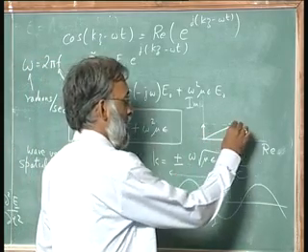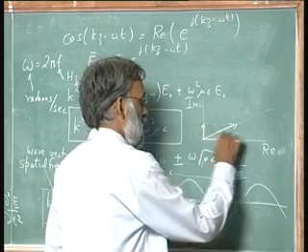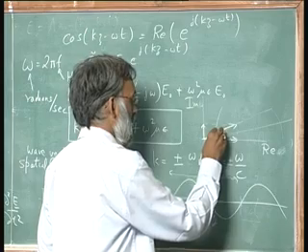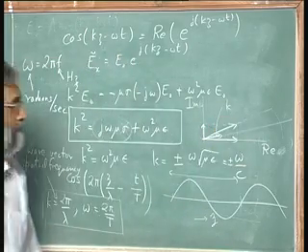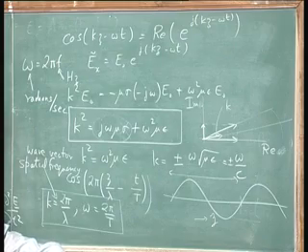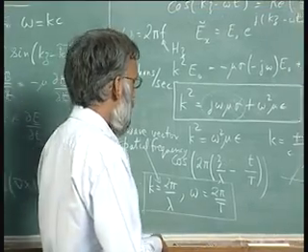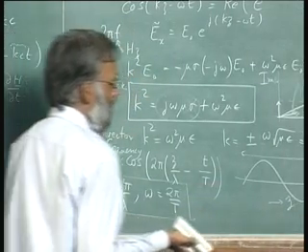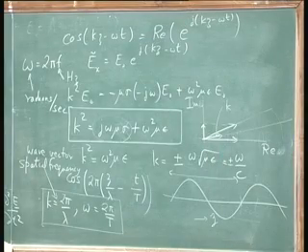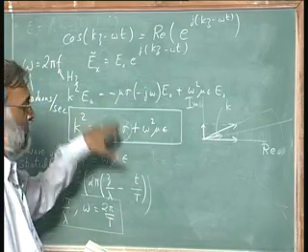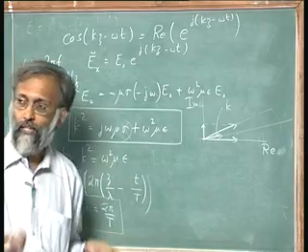So, when I take the square root of that, this angle gets bisected and the magnitude I take the square root, that is my k. So, in general k is quite complicated. However, there is a very simple special case, which is also the most important simple special case. And that case is the case where I can ignore omega squared mu epsilon in favor of j omega mu sigma. Copper is an excellent conductor.